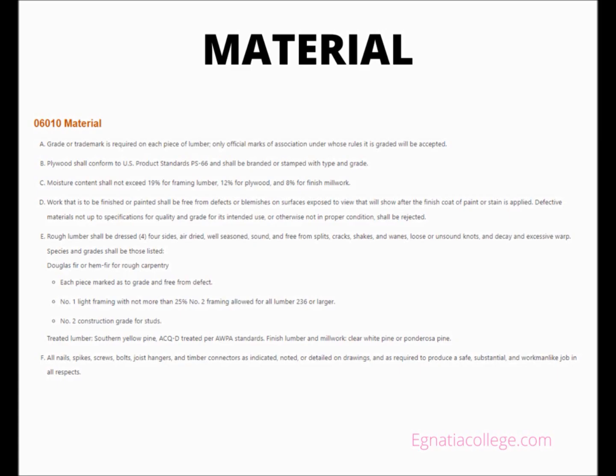Treated lumber, southern yellow pine, ACQD treated per AWPA standards. Finish lumber and millwork, clear white pine or ponderosa pine. All nails, spikes, screws, bolts, joist hangers, and timber connectors as indicated, noted, or detailed on drawings, and as required to produce a safe, substantial, and workmanlike job in all respects.